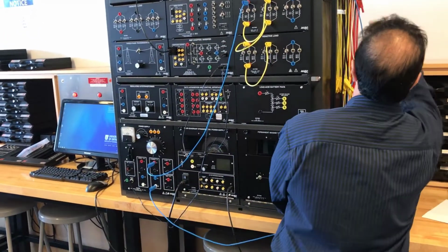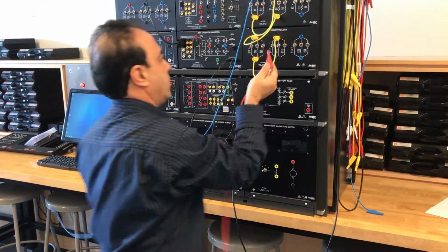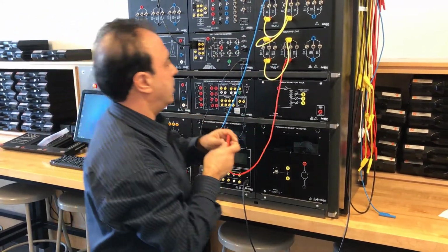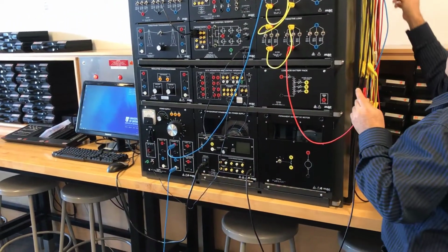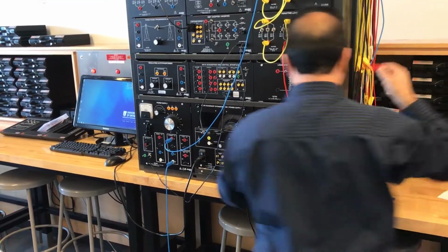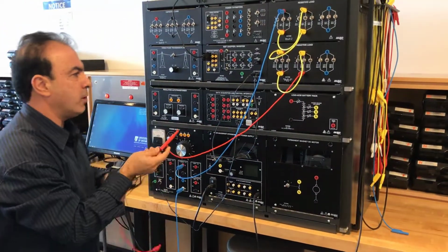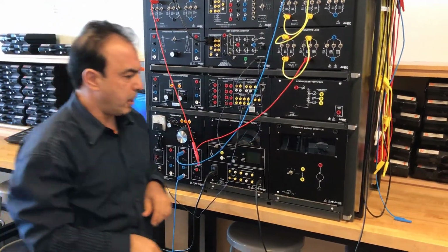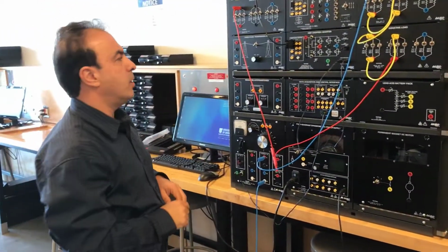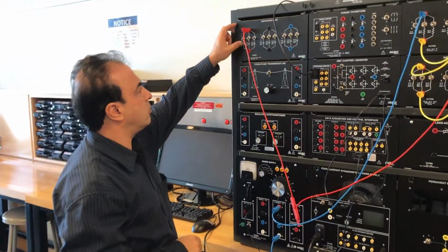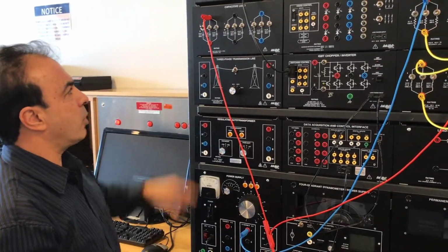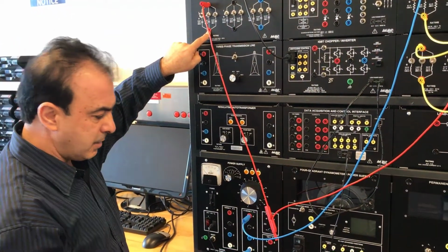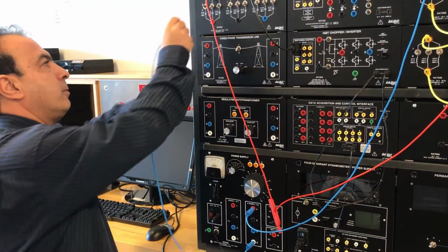So I need a longer cable. I'm going to use this one. I need a bigger one. So I always can extend them. Try to use the same color to extend them. So this goes to the capacitor. My capacitor is 2.2 microfarad, so all I need to do is just to turn the first switch on. That's the switch for 2.2 microfarad, and that would be the end which goes to the neutral.